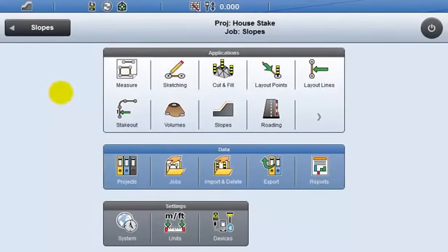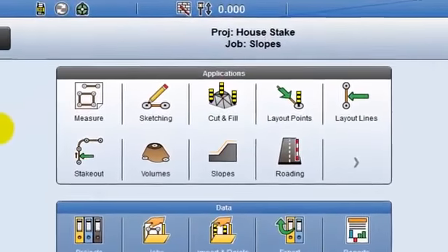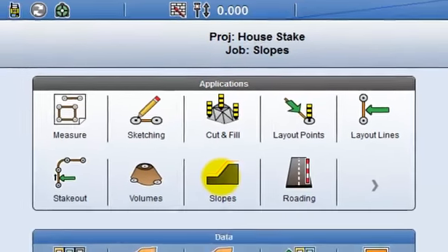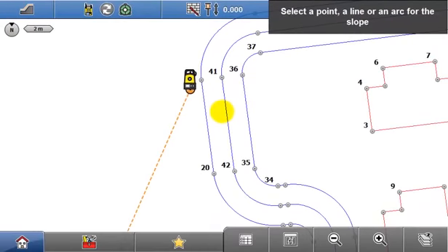The new Slopes application in iCON allows you to quickly create reference surfaces based upon elevation and grade, which can then be used to set up profile boards to guide excavation, and also to perform regular comparisons between actual position and design. These reference surfaces can be defined by specifying the grade of the profile you need to work at and how it is positioned relative to the point and line data in your working area.